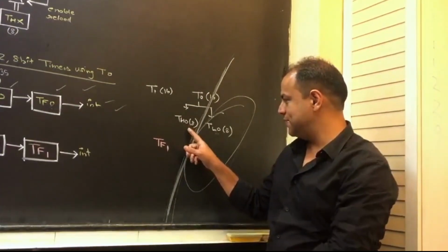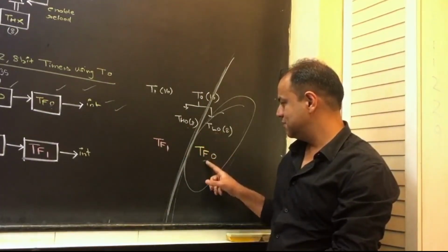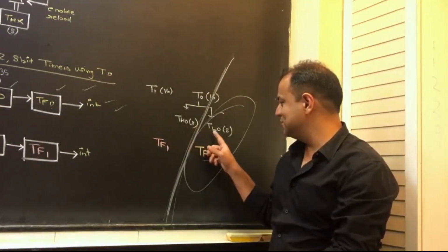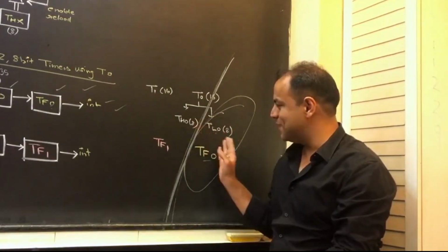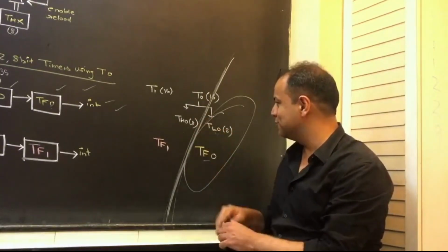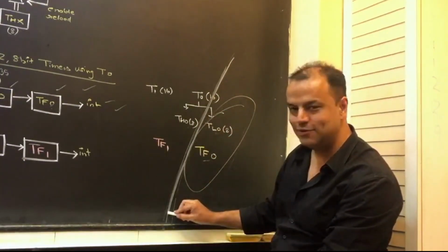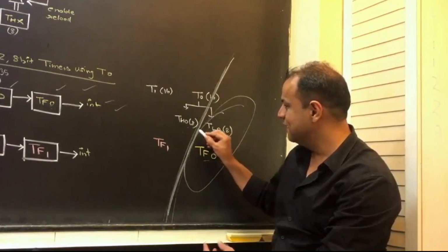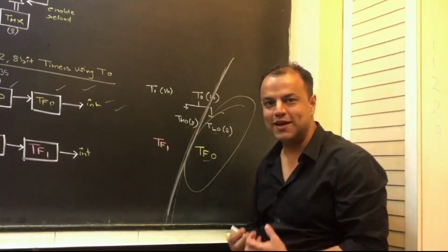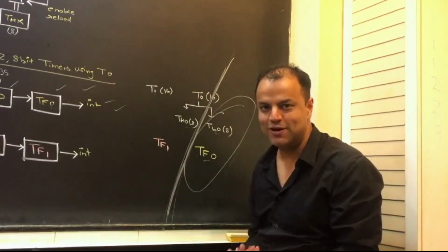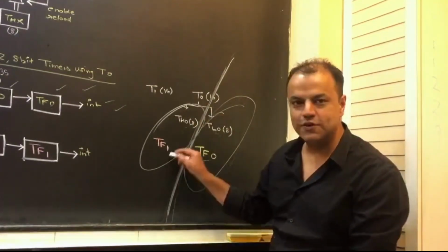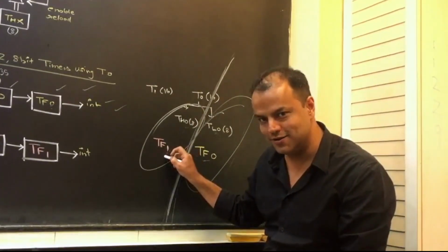So timer 0 higher byte cannot use it. It tries to tell timer 0 lower byte, this flag was both our flags, it was for both of us. Timer 0 lower byte says, no, I'm done, don't come here. This is my flag. Timer 0 higher byte says, it's urgent, I have overflown, I have to do something about it. How do I tell the processor? It uses the overflow flag of timer 1.